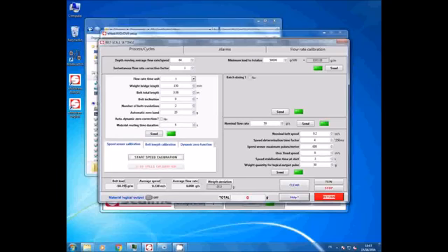We will adjust the minimum weight of totalization. To do this, look at the belt load and set the minimum weight of totalization to make the load correspond. If your total is changing, your minimum weight is too low. Increase it until you have no longer evolution on totalization.